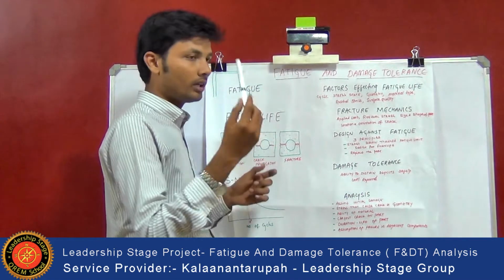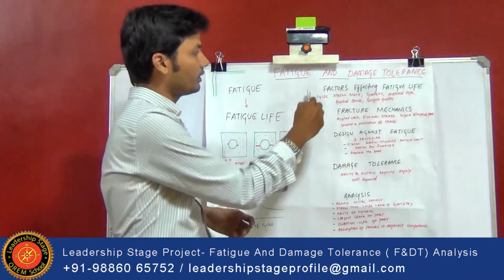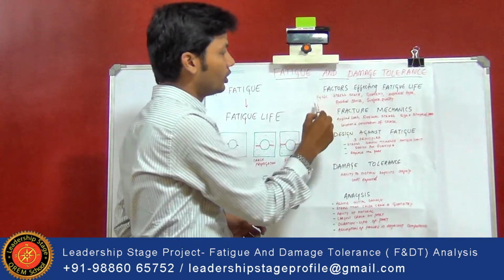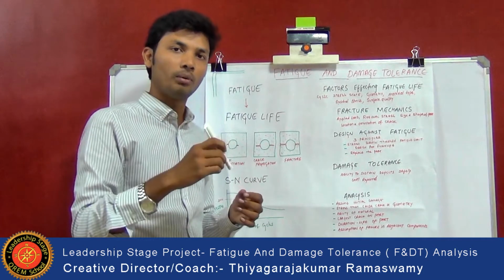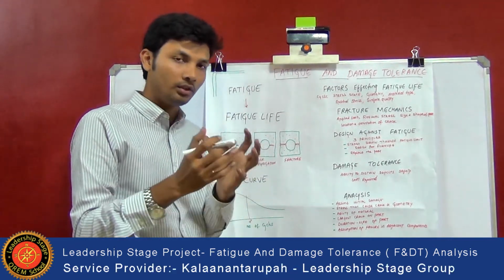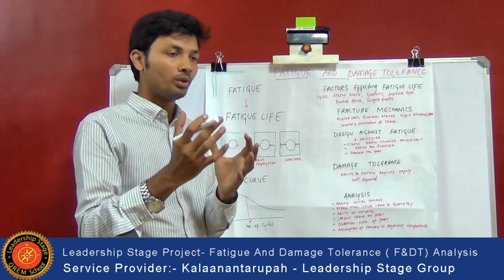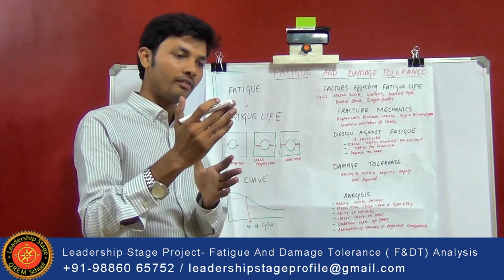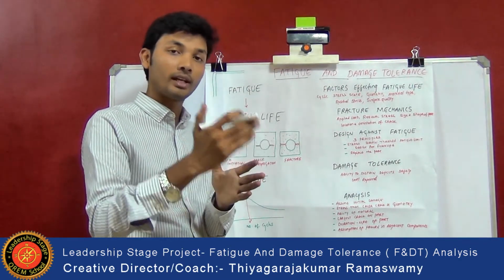So the main factor which actually causes the fracture is the cyclic stress state. We need to study what stress is being applied on the component, and see if there is anything we can do to reduce that stress, so that we can improve the fatigue life.